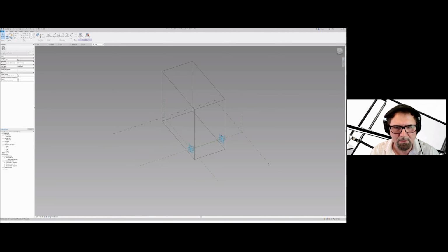Maybe I can just touch up on some details here. Clearly, this is using the reference geometry, also the adaptive components. Very simple. Those 2 points are made adaptive. They go from the host plane, reference surface, all the way to the other one, and then they're connected with a reference line, like you can see.